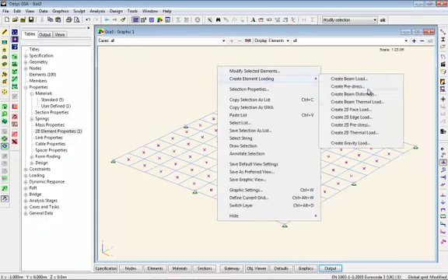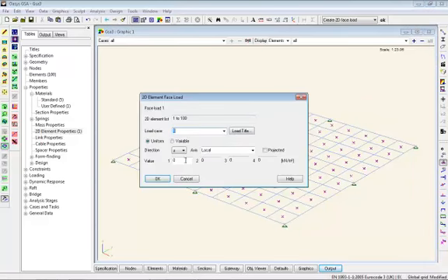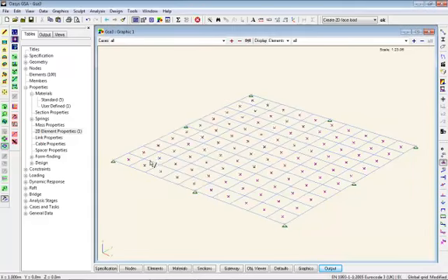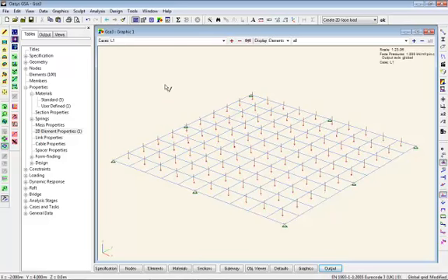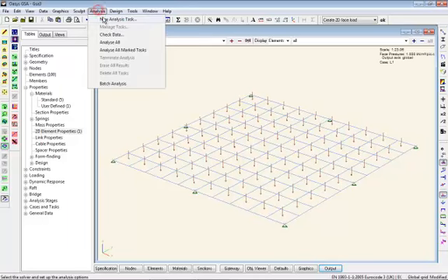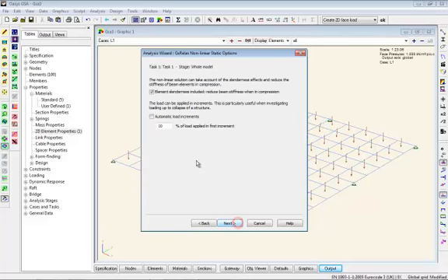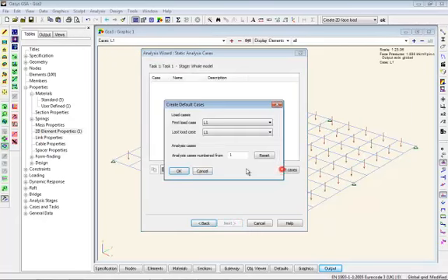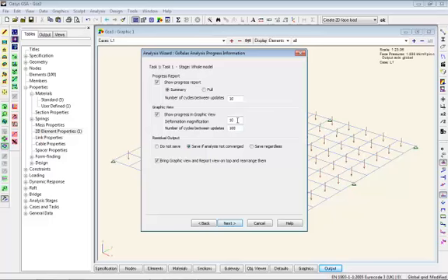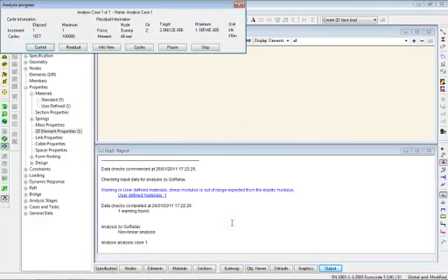And let's create a 2D face load, just a simple -1 load on that. So we're ready to go for the analysis. I do a new analysis which is a non-linear. Default loads. Don't bother magnifying. It's going to move quite enough as it is. Remembered everything.